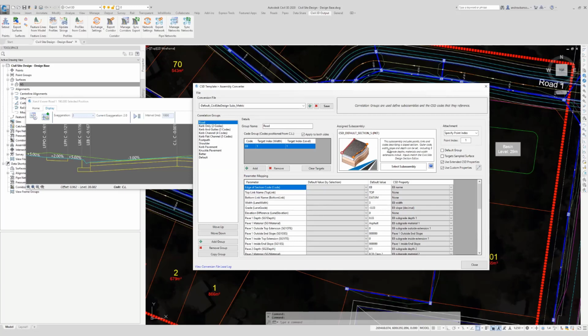And say, for example, this default section, there's a lot of things you can do with Civil Site Design sub-base. I mean, you can extend it beyond its section, and with that extension, you can change the slope and all of that type of thing. The stock sub-assemblies that came with Civil 3D didn't really handle those types of things the way that we do it. So we built our own sub-assemblies, and for a lot of those different parameters, we're able to get a perfect match.